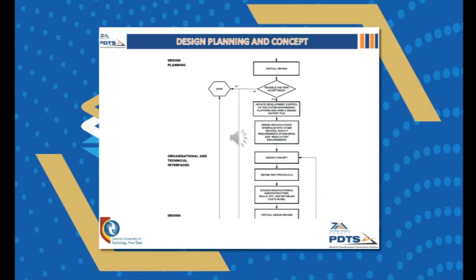A developer shall develop concepts by making use of various design configurations until the design satisfies the input requirements and specifications. All steps in the development process will be documented. Design calculations should be documented for later reviews. Once the design is complete, all drawings, sketches, and specifications should be numbered internally, and an internal revision number should be assigned to it. Once the drawings are approved by the client, a drawing number or document number shall be assigned to it.